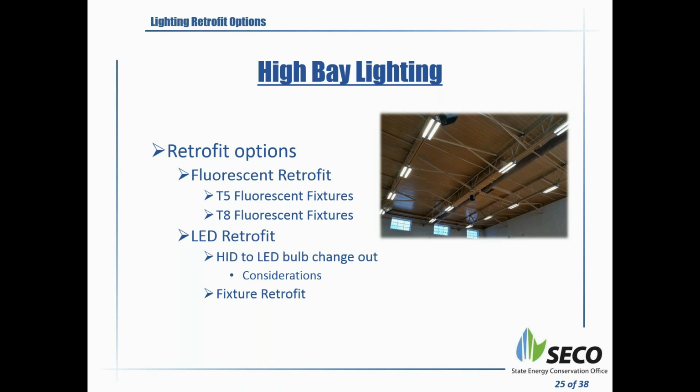LED retrofit, HID to LED bulb change out. So there is also an option where you have the HID fixture, and you can just take the lamp out and put an LED bulb in there. Some people have different results as a result of that. So it's something you want to actually test before you order a couple of hundred of these lamps to replace in your gymnasiums and so on and so forth. So that will be the HID to LED bulb option.